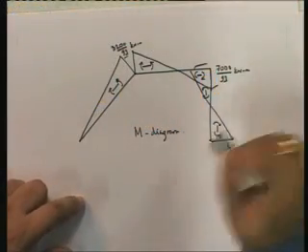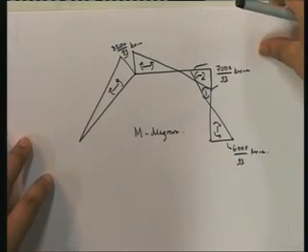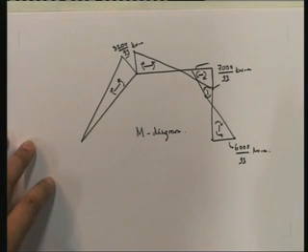Once you've got the member end forces, you've got a structurally determinate member. You can draw the bending moment diagram for each member, put it all together, and you have the bending moment diagram for the structure. Okay, this in essence is your, what am I calling it? Displacement method.